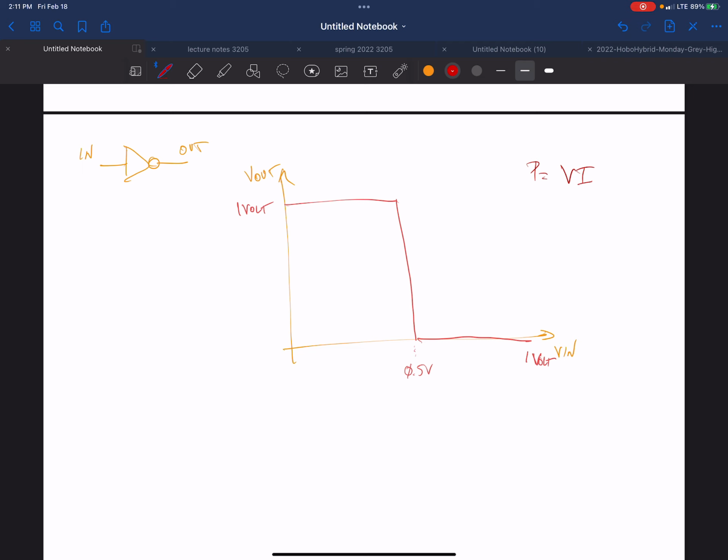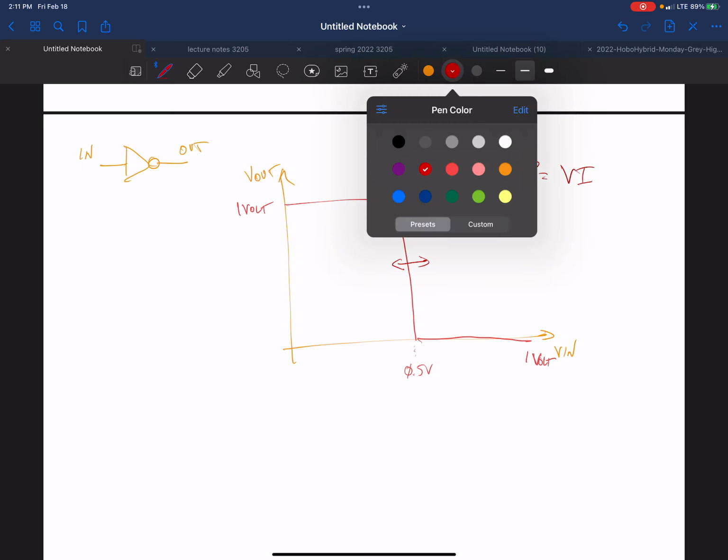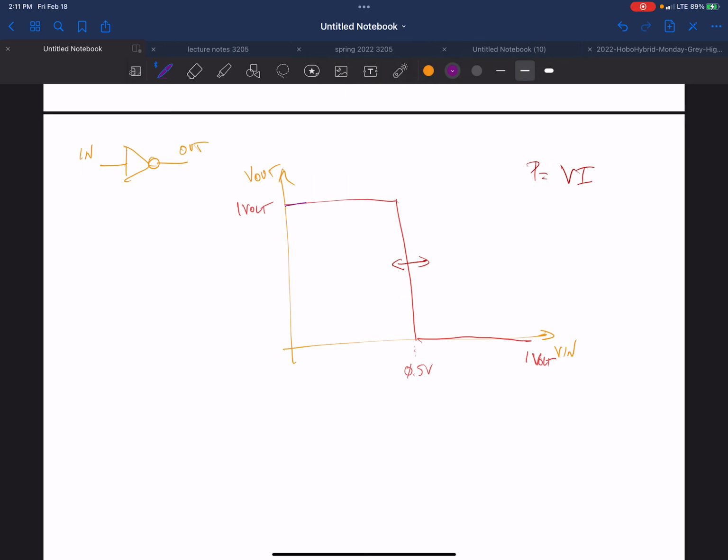So, the other thing that the CMOS logic family does is it's very easy to tune the location of this crossover point. Very easy, easier than other logic families, not completely easy. And you guys will talk about how you can size your NMOS and PMOS relative sizes, and you can adjust this. So what a real CMOS inverter looks like is kind of like this.